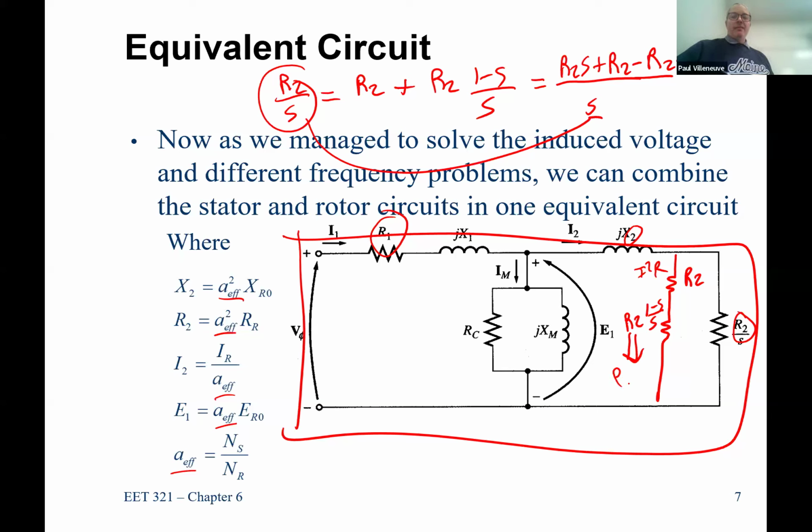Yeah, that's P mechanical. So remember, our mechanical engineering friends are only using this motor because they need drive torque. But electrically speaking, we need to provide enough input power so we can drive that mechanical load plus all the losses in the machine. So we just characterize the power provided to the mechanical system as R2 times (1 minus S) over S.